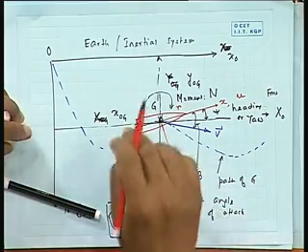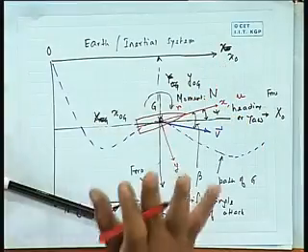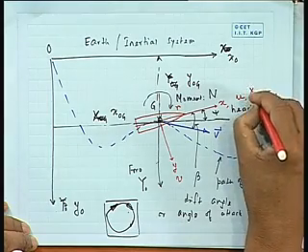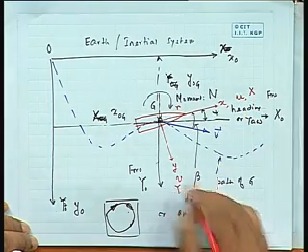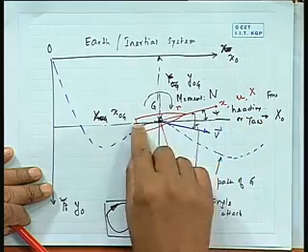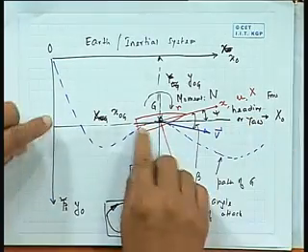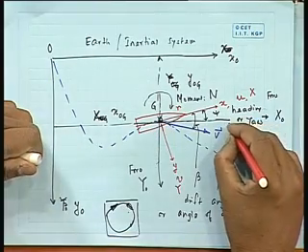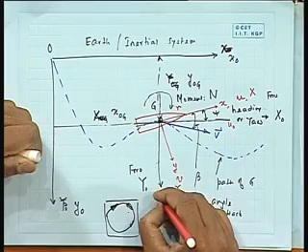Normally it is called r, where r equals psi dot, the rate of change of the heading angle. We will come to that a little later on. But understand this: let me call this x and this y, and I am going to call the force on this side X and the force on this side Y. So there are two systems. One is along this line, where I have a velocity x_og dot, which I can call u dot, and this one I can call v dot.